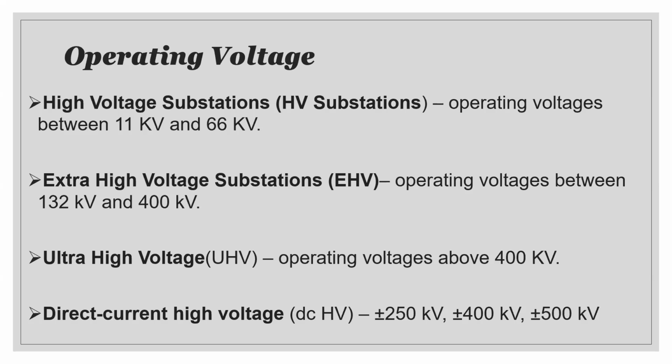Do you agree with that, even if you're not sure? So they are at 60, but they are selling electricity to England, which operates their system at 50. Remember now, the generators in England are operating at 50 hertz, just like it operates here in Jamaica. But in order for them to purchase power from overseas, just like they're purchasing rice, for them to purchase electricity and use it in their system, which is operating at 50, we need to convert the 60 to 50.